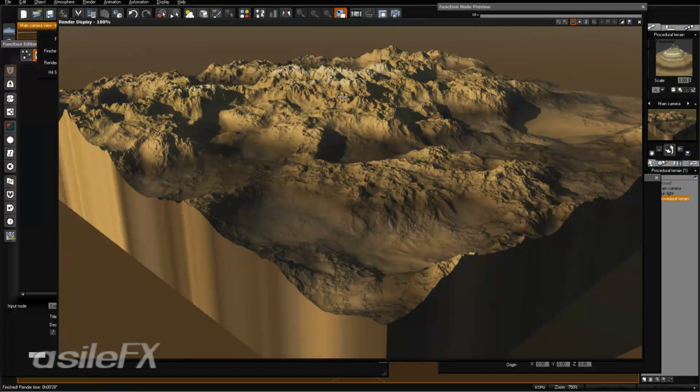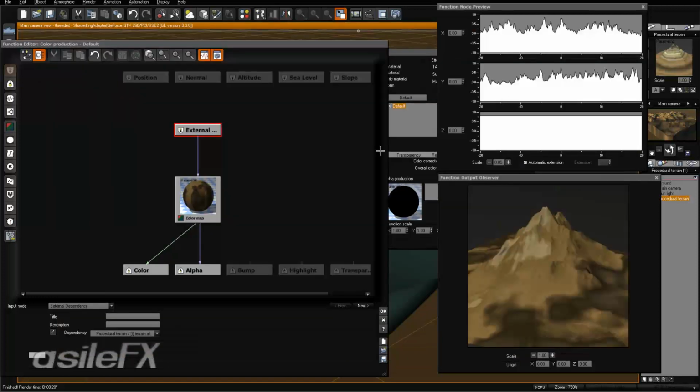Now we see vertical lines throughout the edges of the terrain, representing where the highest areas are, and that kind of going through into the sides. Because the altitude that is output by the terrain editor is going to be two-dimensional. The 3D information along the Z is not used to create a procedural terrain. The only time that information is used is when you're using planetary terrain for spherical scenes. But otherwise, the Z information is completely null and not used at all. So this becomes a projection onto the X and the Y, with the Z not being used. So what we need to do is use this information to manipulate the altitude information.